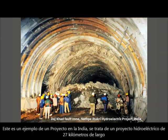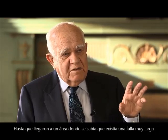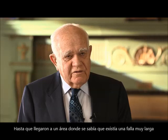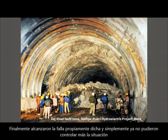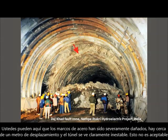Here's an example from a project in India, a hydroelectric project, a 27-kilometer long headrace tunnel to a hydro project. And in general, the tunneling was good, but they reached one area where there was a known very large fault. And as they approached the fault, the ground got worse and worse, so they started installing steel sets. And finally, they got into the fault proper, and they simply could not control it. You can see here the sets have been severely deformed. There's about a meter of displacement, and the tunnel is clearly unstable, not acceptable.